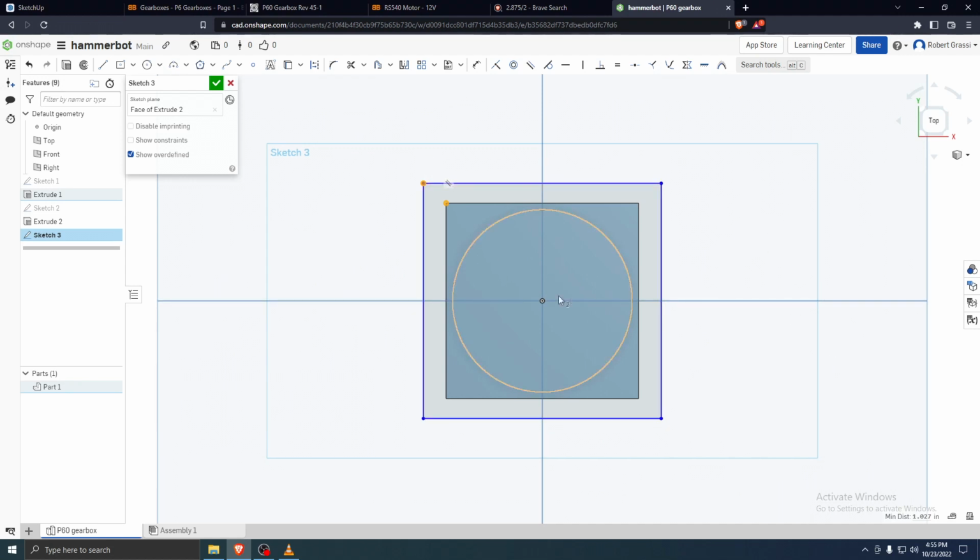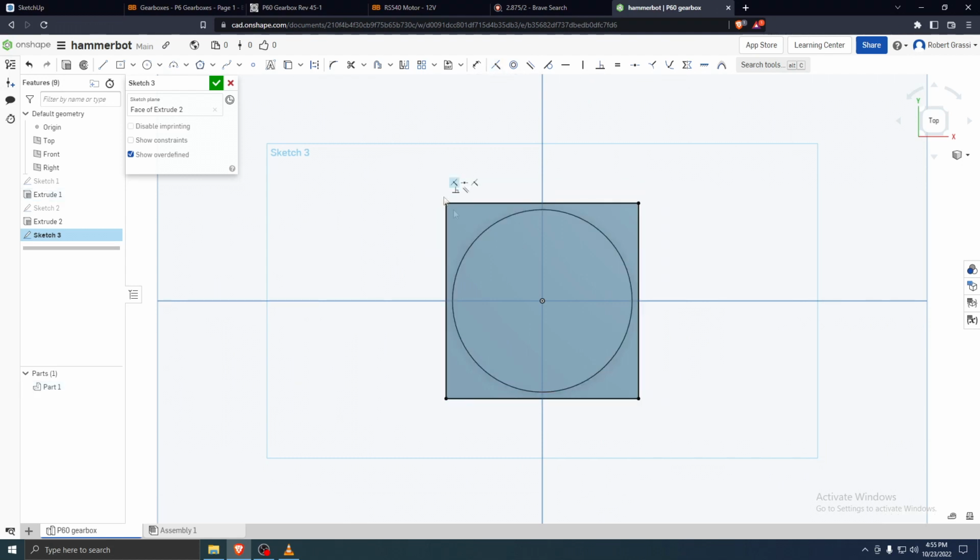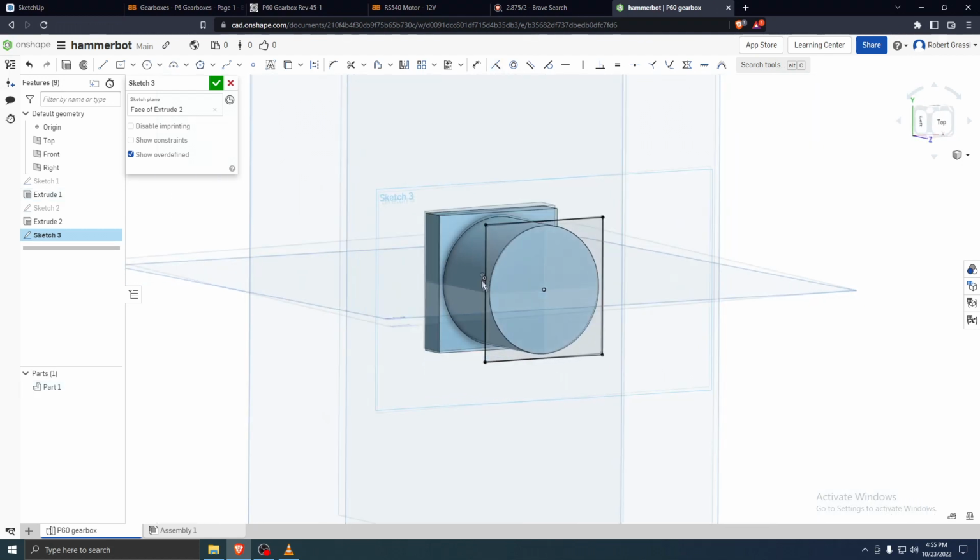It will just continually select them. And we go over here, and these are ways that we can combine lines into each other. So we can make them coincident, meaning make 2 or more sketch entities share the same location. So we click on these 2 points, and we want them to be on the same point. We hit coincident, and then it will automatically go to that distance.